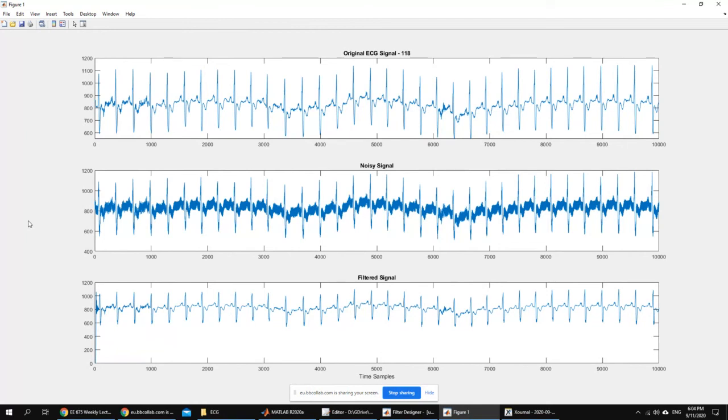Basically, for the noise, we knew that the noise is at 60 Hertz. For the actual artifact that we're going to work with, we really don't know that information. So this will add a new part where we try to estimate that frequency and then experiment until we get it exactly the way it should be. Okay.